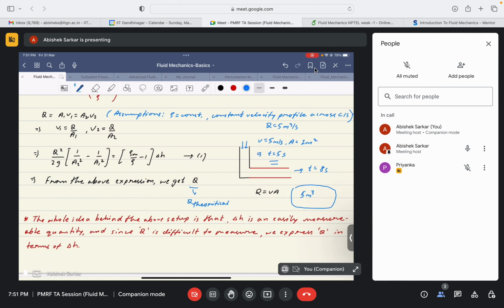Are you getting an idea? Yes, sir. The volume of water would remain the same, but its flow rate would decrease because of what? Because of friction loss, that has caused the velocity of the flow to go down, right? Yes, sir, the velocity of flow will go down.